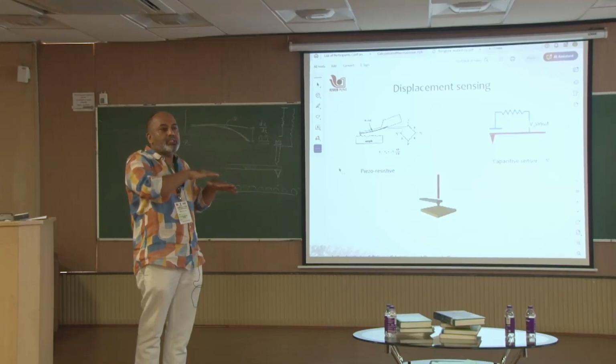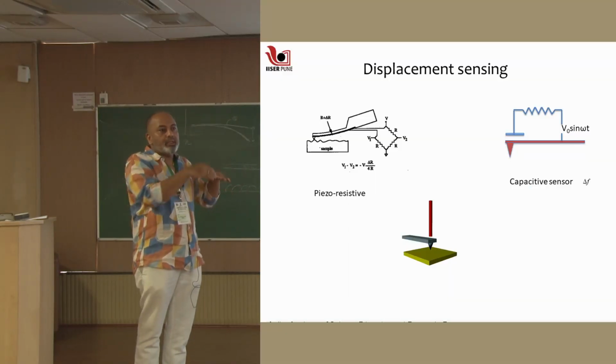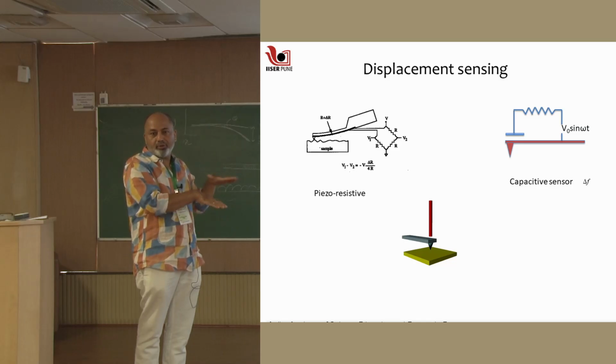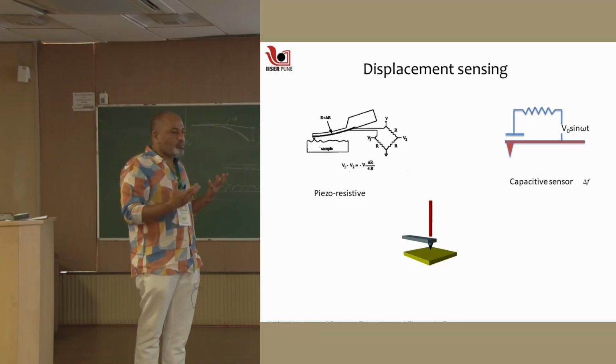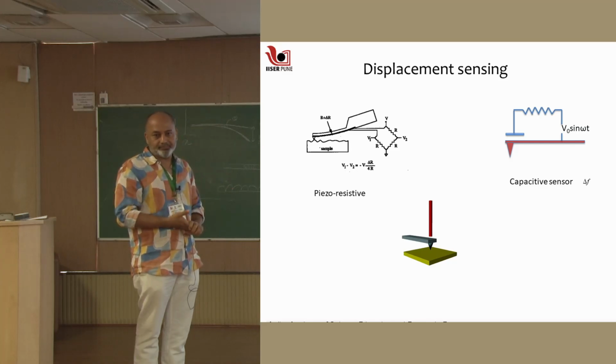And typically if you increase the number of junctions, it will have a lot of drift issues, this issue, that issue, sometimes you will end up scanning or measuring the back of the cantilever instead of the thing below, right? Because you scan the whole thing. So it's all problematic. And very quickly, right after the first paper, the inventors of AFM themselves realized that that way of measuring cantilever bending is not really a good idea.